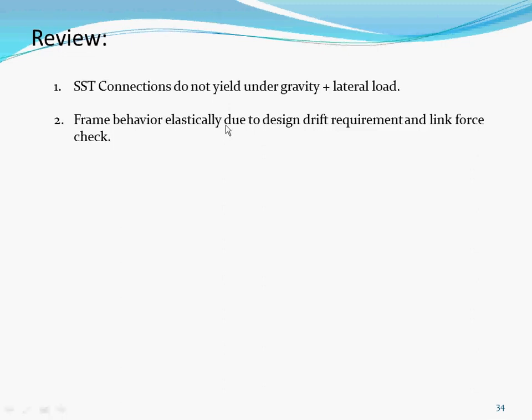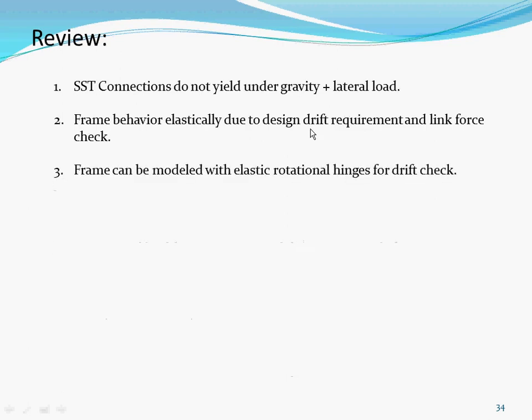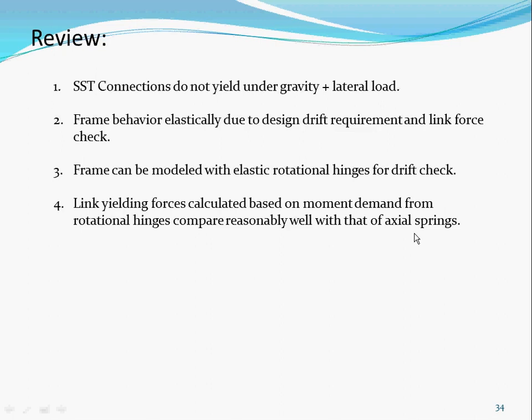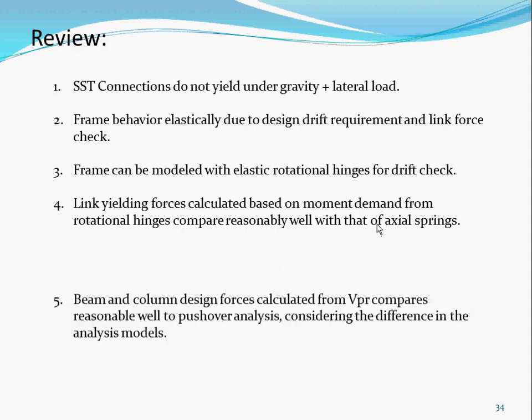The frame behaves elastically to design drift requirements or link force. Model with elastic, or the other one with the hinge, for the drift check. Link yielding force is calculated based on moment demand or from the spring. You can actually read it off the spring in SAP. That's one good thing: instead of having to calculate a moment divided by the depth, in SAP you can just read off what the spring axial forces are. So there are different models for how to do that.